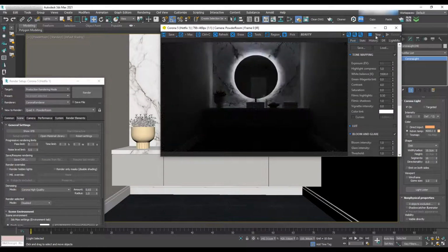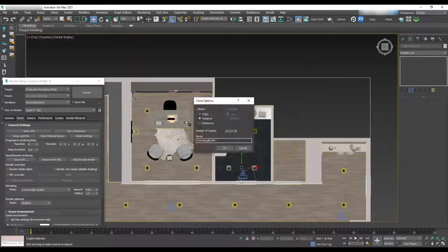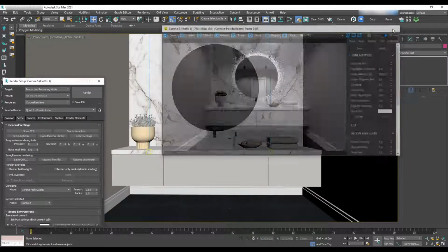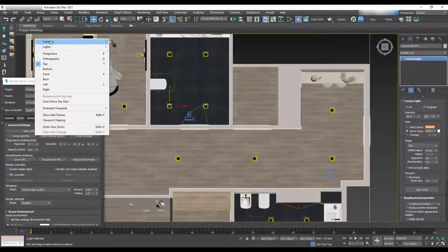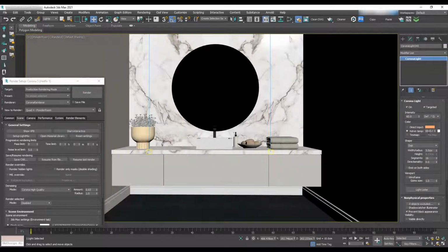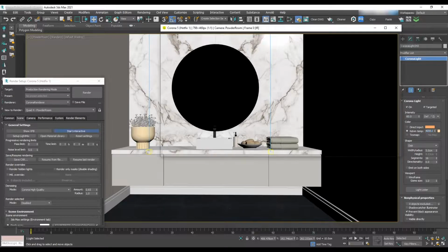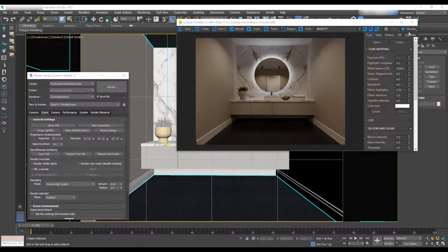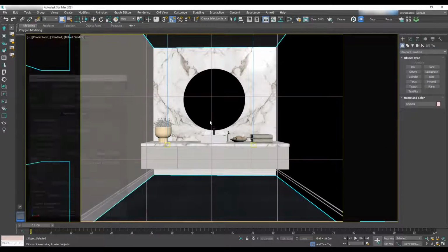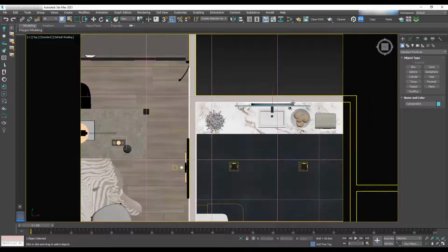Let's do a test render first and then copy paste the IES. We need to change it to a warmer temperature like 4000 or 4500. It's looking pretty good. Before submitting renders, we'll need to set a background photo.